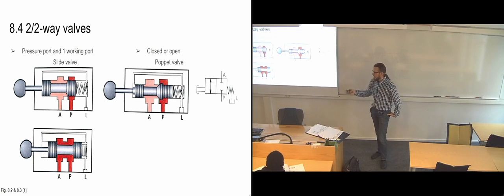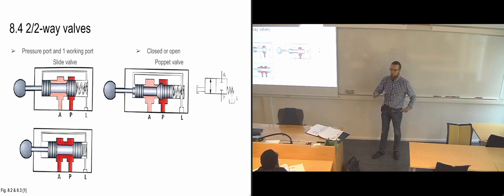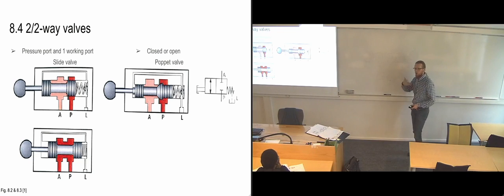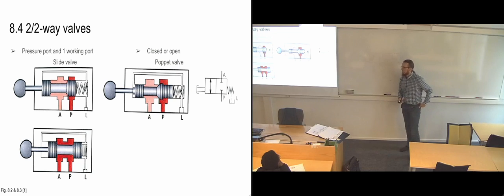It's still going to close off the P port, most likely, definitely if you have a positive overlap, and you're going to be able to see it once the push button is pushed out there. So that's one thing to keep in mind. And that's going to happen, since with a slide valve you have leakage from the start. The older the valve is, the more it has been used, and the more wear and tear, the more leakage you are going to get. So very old valves can be a problem with too much leakage.